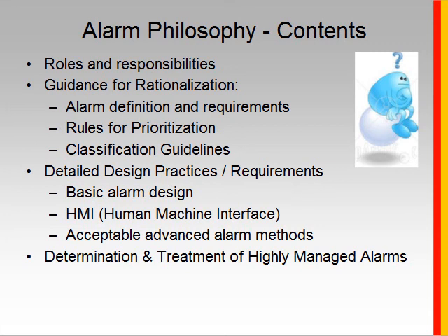Other things that go in the philosophy, again, this is a document. It's going to describe the roles and responsibilities and really define the guidelines or the standards that you will use for the different phases or stages of the life cycle. Rationalization is a very important one. We'll talk about that in a second. But in that, we want to define what are the rules that we'll use for prioritizing and classifying alarms. We'll talk about what colors we're going to use in the HMI and annunciation for indication of alarms to the operator.